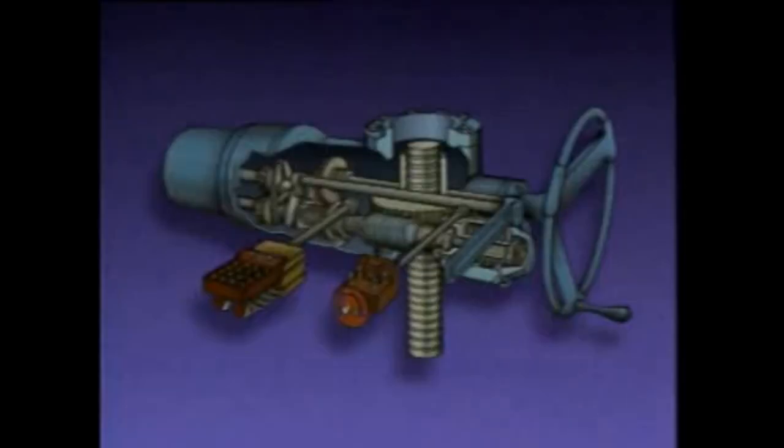For example, the limit switch on this motor operator shuts off the current to the motor when the valve is fully open. Now, even though a motor operator consists of many different components, it's usually represented by a single symbol on a piping system diagram. This is one example of a symbol that may be used to represent a motor operator on a piping system diagram.